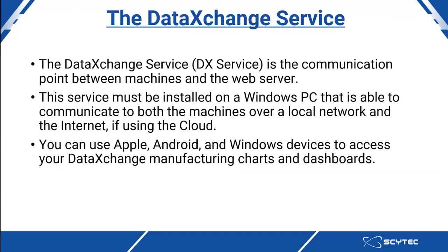Next up, I'd like to be discussing the Data Exchange service, which builds off the last slide that I just went over. And the Data Exchange service, which we affectionately call the DX service, is the communication point between machines and the web server. This service must be installed on a Windows PC that is able to communicate to both machines over a local network and the internet if using the cloud offering.